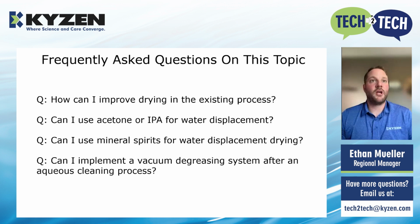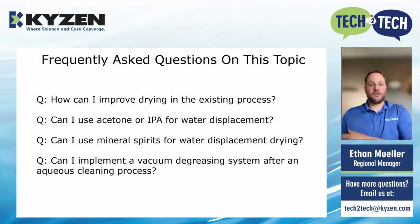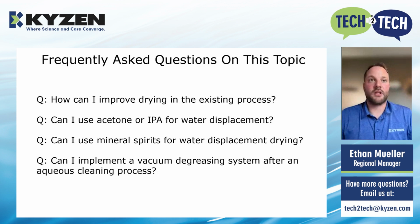Can I use mineral spirits for water displacement drying? Yeah, mineral spirits are often used in this type of way. They are not very volatile and they don't dry quickly, so it really depends on what your downstream process is. If you need a dry part that does not have any liquid on it, this is probably not the best way for you. It can prevent other issues associated with water, such as corrosion, where you have this slow evaporating liquid on your part that does not cause rusting, but it's not really to aid in quicker drying. It's more to displace that water to prevent corrosion, and then eventually you go to your downstream process, and hopefully by then it has completely evaporated away.